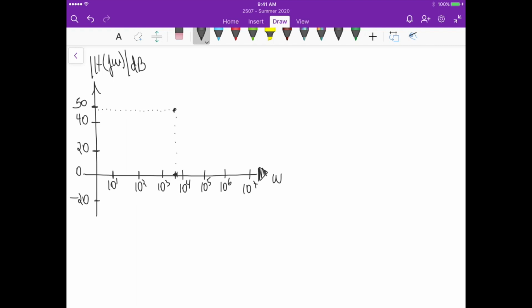Now if we are 10 dB lower than that, we are at around here, and 2 decades below that it's around here. This is just low frequencies, so we are most likely to be here around 50. Okay, you can calculate the exact value. Even here it's going to be around 50 because that's the DC gain that we have specified.